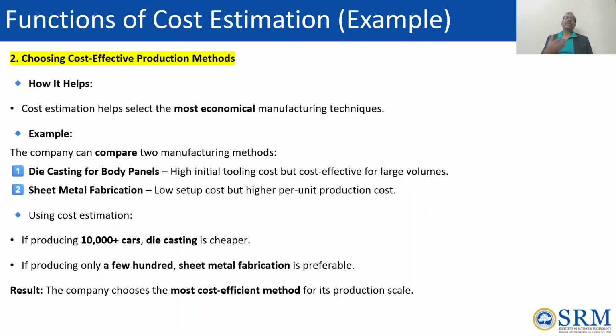Or if we are going to use that investment in the initial tooling for other purposes, instead of keeping those facilities idle, if we have a plan of action for utilizing that tool not only for this application but for other products, then we can. Otherwise, if the volume of that car, instead of a fixed number, starts increasing more and more, then die casting for body panels will be useful and beneficial.